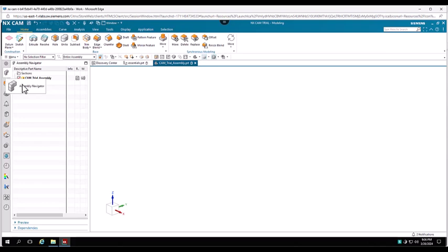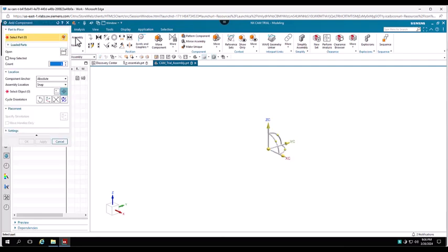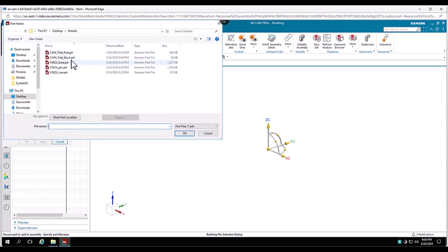and I want to create an assembly with the files that I have translated. So now under Assemblies, you have a few options here. I'm going to hit this Add Component. And I'm going to, under Open, hit this folder here and browse to the part file that I just created. Click OK.